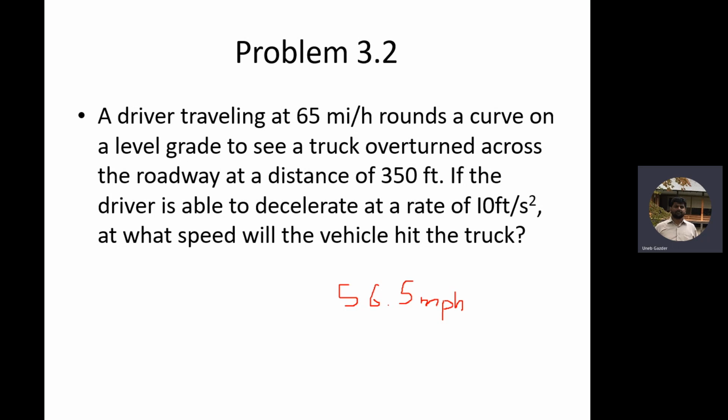The braking distance. You calculate it, something given here in the question. Before you calculated the speed, you calculated what? The f value. F value depends upon deceleration. His deceleration is lower than what is recommended or expected. Okay, maybe the brakes were not good or he did not understand the situation. But the main thing was he did not see the truck from a greater distance.